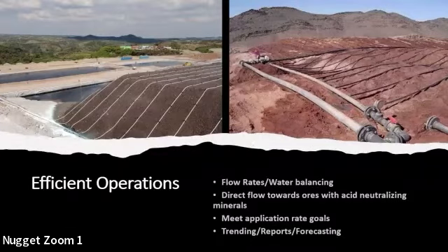So in this case, on average, we got to 15 meters, but 2 out of the 22 tests performed had to be eliminated because one only got down to 5.5 meters, which would be 15 feet, and another one got to 9 meters in depth, which is 27 feet. That is a low percentage of all the performed tests.